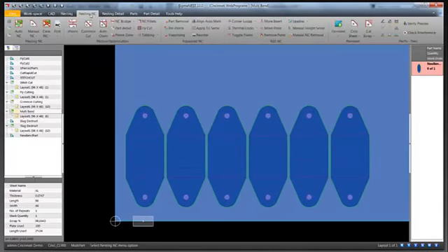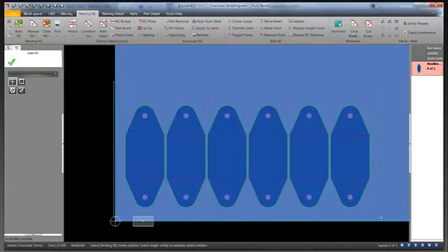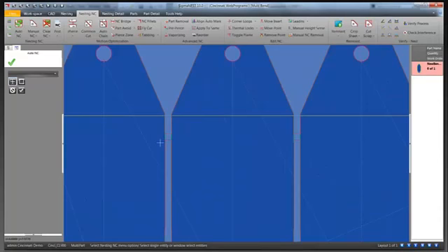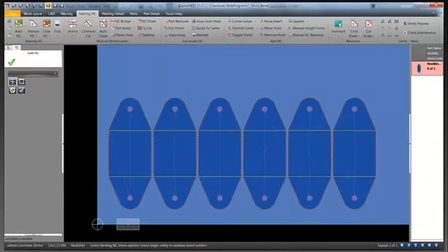And when we put the tool path on it, you're going to see we're going to use this feature here called bridge. And we can define the width of the gap in between these parts that's going to allow us really to break them off. We're using a little bit wide gap right here just so we can see it better. You know, we'd use a much smaller gap in reality. So we put the tool path on it. We're going to simulate the cutting so you can get an idea of how this looks.